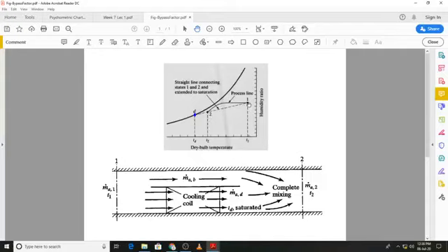And if we adiabatically mix two air streams, 1 and D, what we are saying is that at the end of the mixing we will still attain the same temperature that actually exists at the cooling coil exit, that is state 2. So you can say that state 2 must lie on the straight line connecting states 1 and D based on our earlier analysis of adiabatic mixing of two air streams.